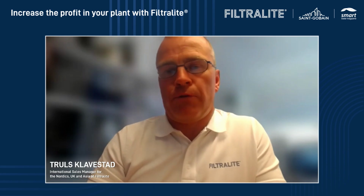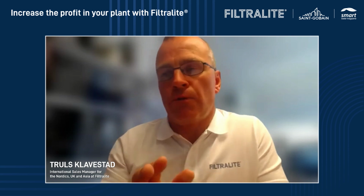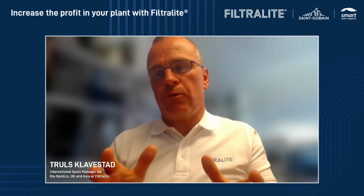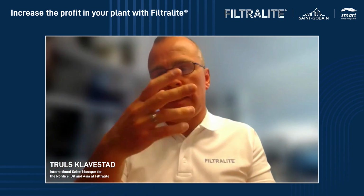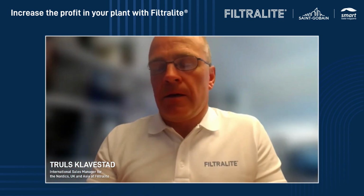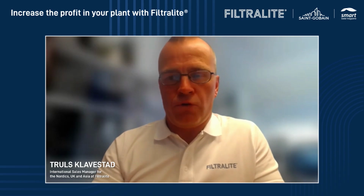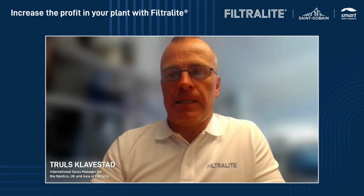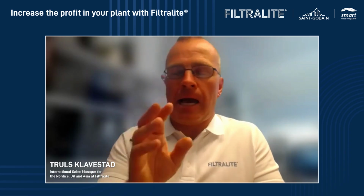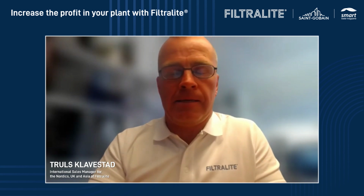It's not so many options for sure, because we supplied to them twice. The first project we did with them was in a gravity filter, and a few years later they put a pressure filter on top of the gravity filter, and they ordered more Filtralite. So based on the Filtralite we delivered, which was Filtralite NC 1.5, 2.5, it's kind of high possibility they have sand around 0.8, 1.2. It can theoretically be down to 0.4, 0.8, but I don't know exactly.